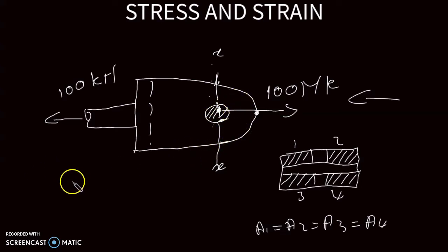So now, to calculate the tensile stress in the fork, we know stress is given by force, which we already have, divided by area. The area is the one that we are going to use from this sketch. So we are going to calculate area number 1 because they are all the same, and multiply by 4, because we are dealing with 1, 2, 3, 4 areas that are experiencing the tensile load that we are talking about. So now our next job is to get the magnitude of the area.